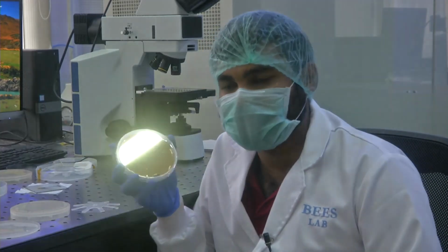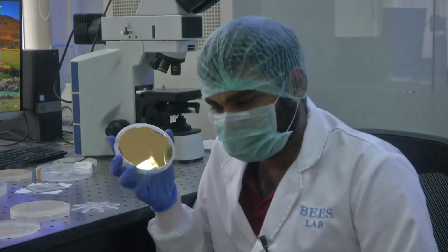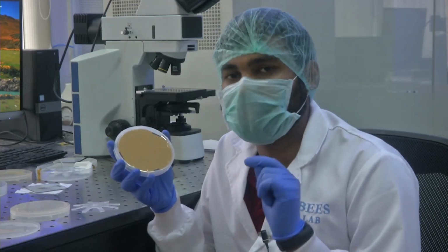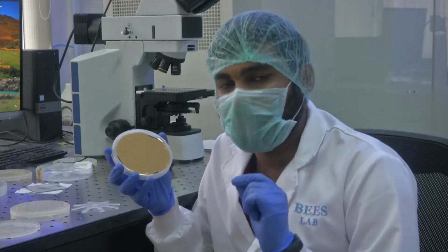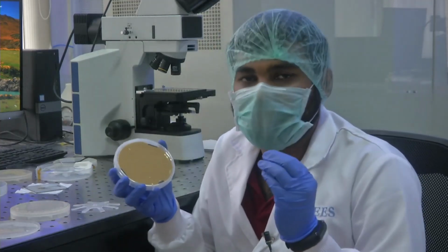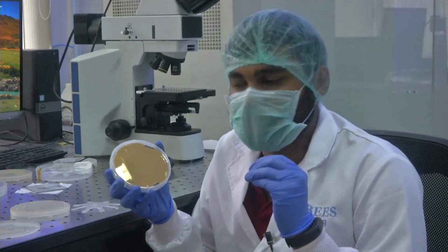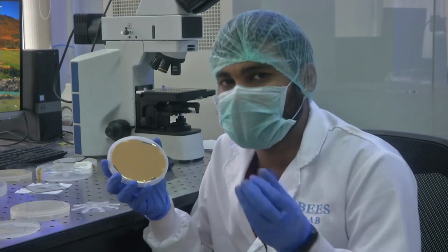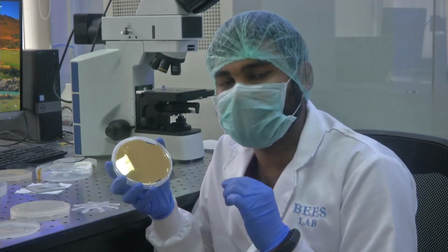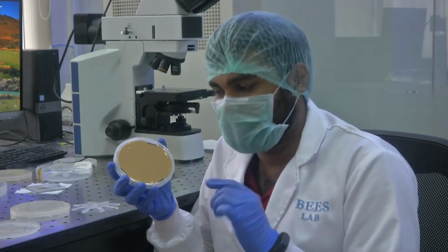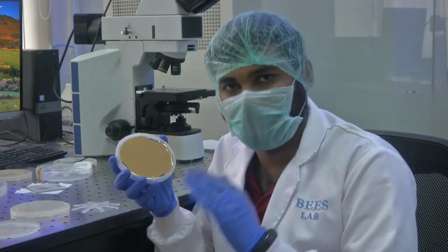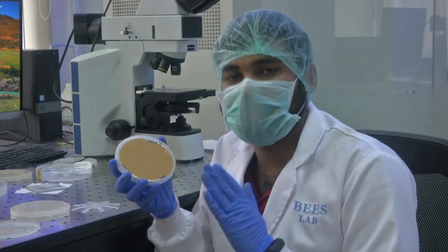Now, how much thickness of gold is there? So this has 195 nanometer of gold, and below that you have 25 nanometer of chrome. Why is chrome used? Gold by default has very little adhesion, or stiction, to the silicon substrate. You might have learnt this in the theory classes, we are just showing it to you. To improve the adhesion of gold onto the silicon substrate, we use a 25 nanometer layer of chrome. First we take the silicon wafer, then we deposit 25 nanometer of chrome, and then we deposit 195 nanometer of gold.